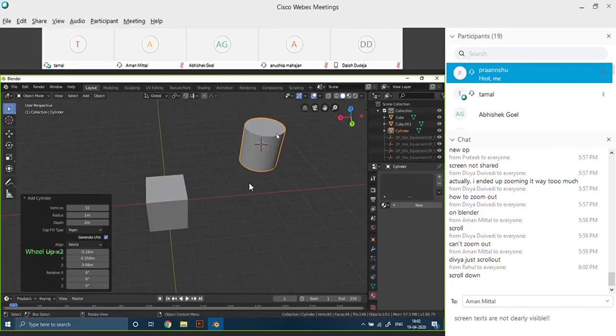I want to add another thing about this. When you add a cylinder or sphere in Blender, a small window comes up from which you can alter its dimensions, its number of vertices. Is everyone able to see this screen? Yes, yes. So you will see this increase and decrease in the vertices. You can also increase and decrease the radius like this, the depth, the height actually.